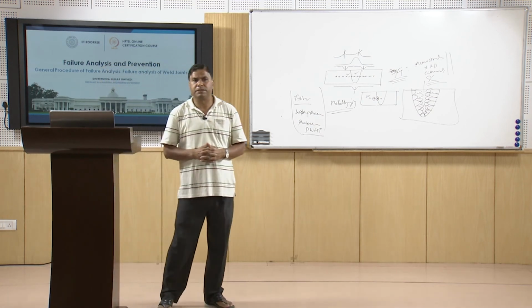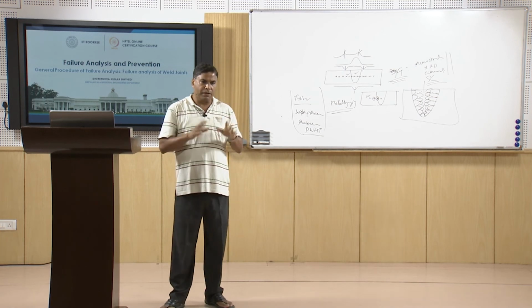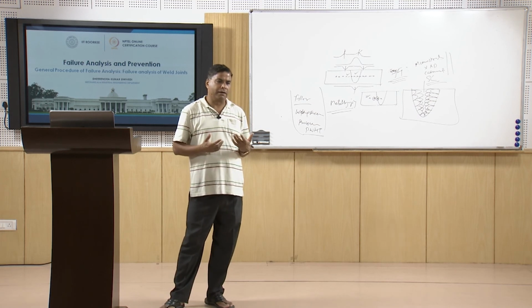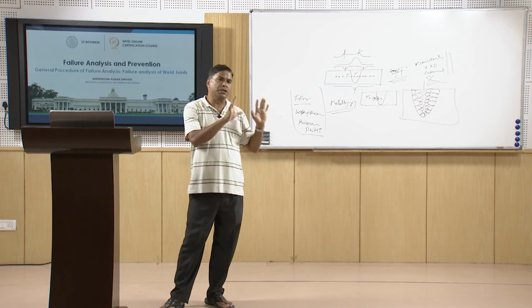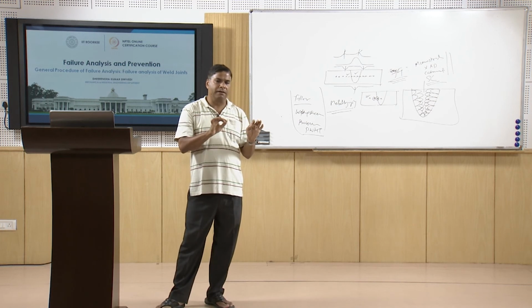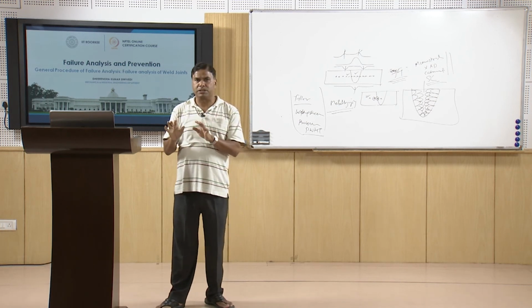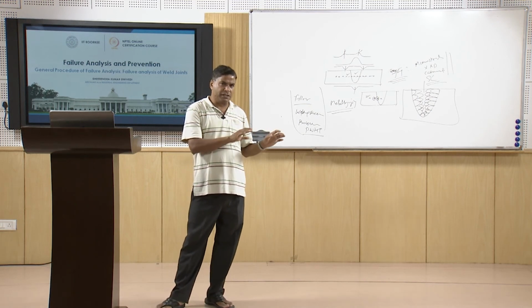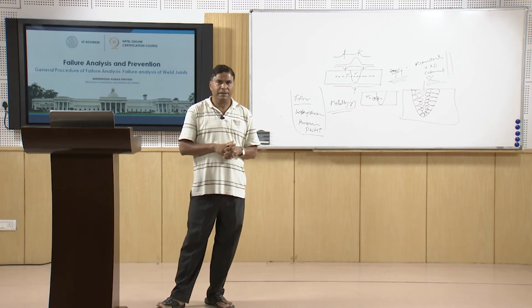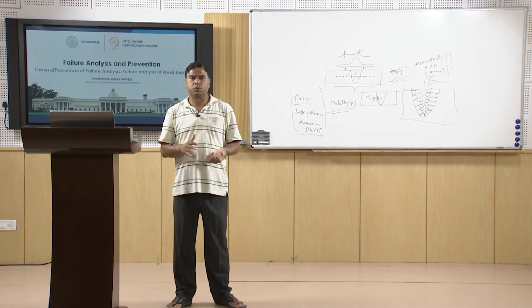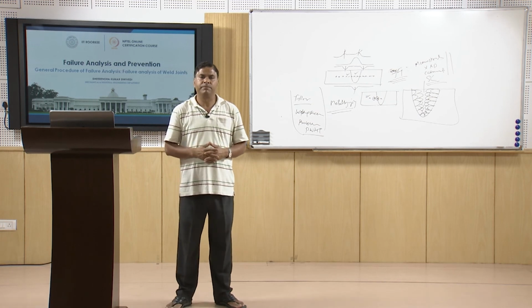Now I will summarize this presentation. In this presentation I have broadly talked about the things we have to keep in mind while carrying out the failure analysis of the weld joint. We need to focus on the locations from where failure has taken place and look for the mechanical, metallurgical and the presence of discontinuities, mechanical properties, chemical properties and metallurgical properties of that particular location, so that we can have a better idea about the things which would have led to the failure of the weld joint.